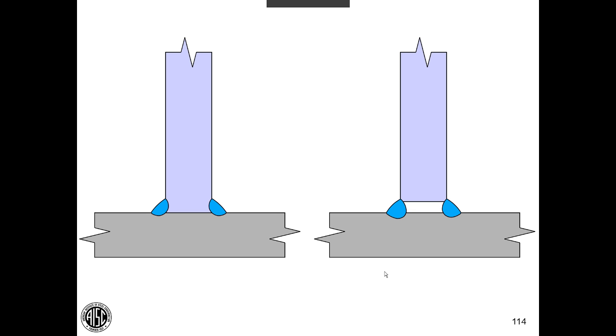Okay. Well, first, AISC 360, the steel spec, Chapter J has a variety of cartoons with formulas to calculate stresses around the perimeter of tubular connections. And it's reflecting the fact that we don't have the same stiffness on all elements of the tubes.